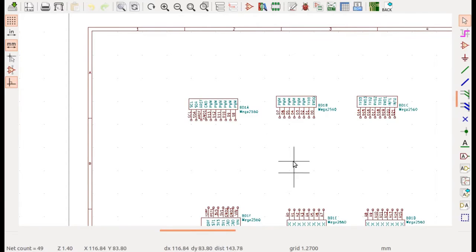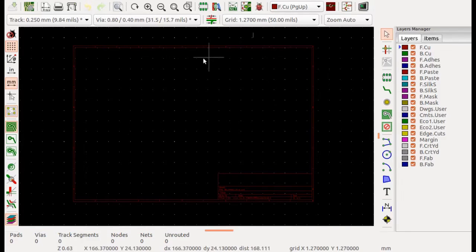And so now we're prepared to go over to the printed circuit board. We can actually do that from here. We can click on this button right here, which will take us to the printed circuit board layout editor. And notice when we come over here, there's nothing here. It didn't come over. We have to actually tell it to bring it in. So we go up here to the top and click on this update PCB from schematic.